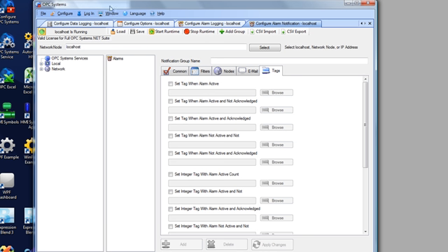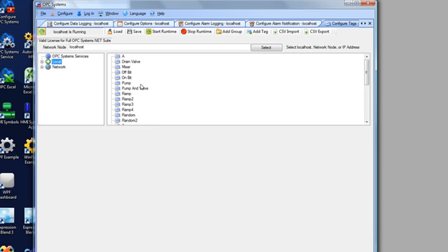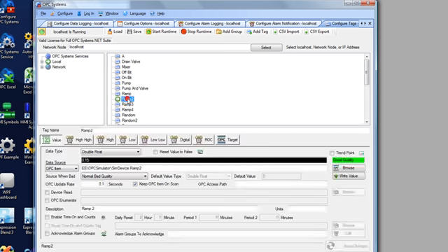Now let's review remote OPC connections. We'll see that the best implementation is to take advantage of the OPC system service as a service-oriented architecture to have all OPC Systems.net tags or direct OPC items always connect to a local OPC server. That's your best option as far as reliability and ease of setup.